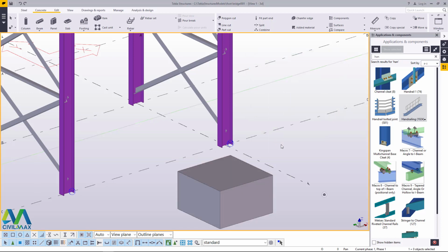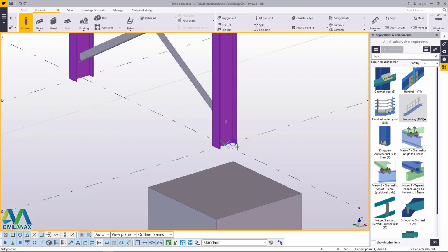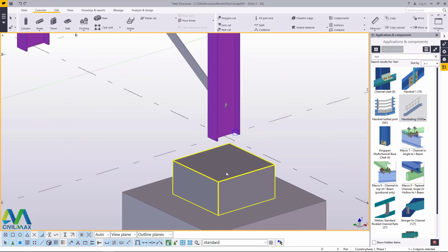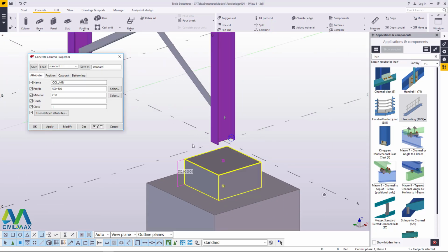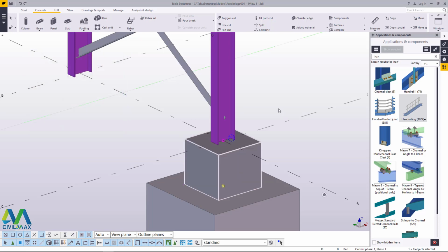Then on top here, I'll place my column base by coming to concrete and picking on the column and snapping at the bottom end of this steel beam or steel column right there, and that's it. It has gone way off the 00 level, and if I double click to check that, you can see it's negative 200 off the 0 level. Now I bring this to 0 level by typing 0 there, and it will come back to that position.